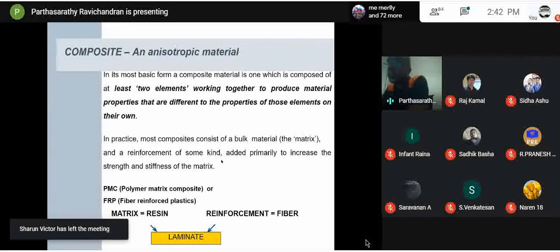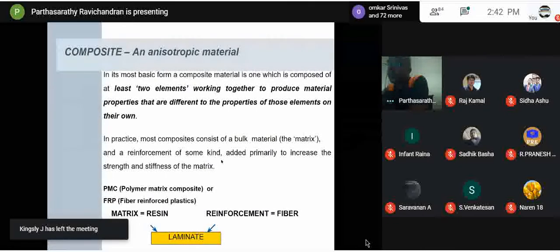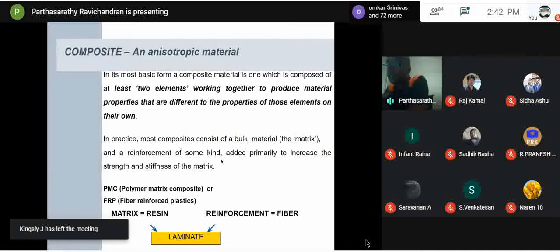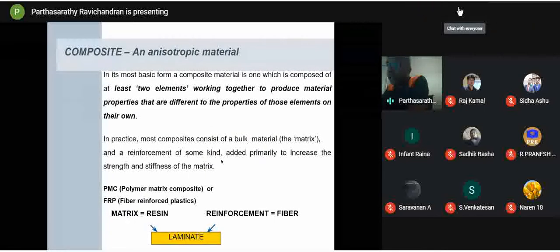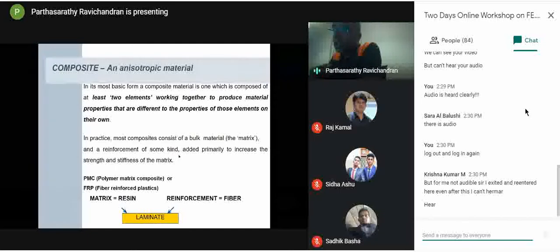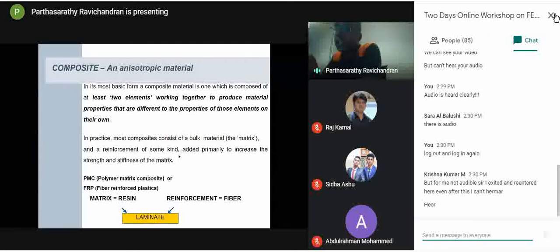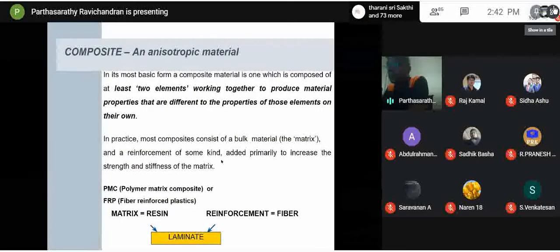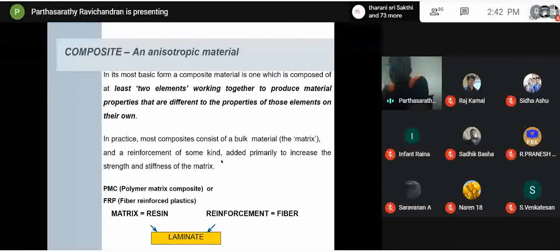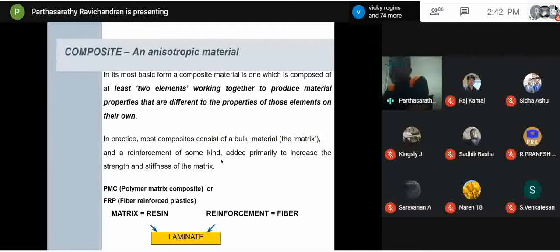But whereas in thermoset composite material, that's not the case. The fiber orientation plays the major role. For example, if you take the blades, the whole length of the blade is where the fiber orientation is mainly concentrated, and then they would have a warp and weft across the other directions as well. But the majority is in the length direction. Since the blade is cutting through the air, they will have 0, 45, 90-degree orientations of the fiber. This is how it plays.